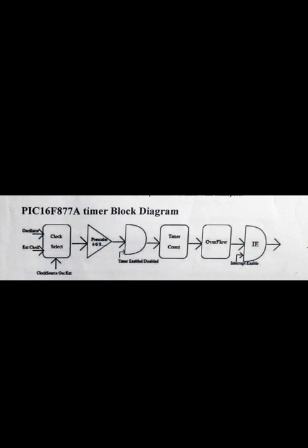The timer is used to count cycles and perform a particular action at a specified moment, or optionally start the interrupt cycle. The digital cycles counted by the timer can be supplied internally through the peripheral clock or externally through a crystal. In this article, we will see the details of the PIC 16F877A timer.